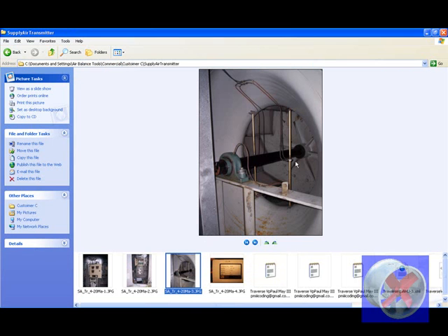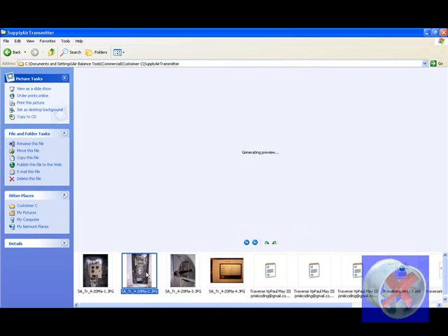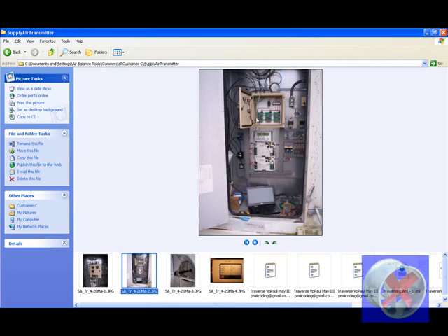Okay, so at the inlet of this fan, we have our pickup tubes. The diameter of the inlet of the fan is 42 inches. We have a transmitter that's rated, and the only thing that we know is it says it's 88,000 cubic feet of air per minute that this transmitter is rated for.